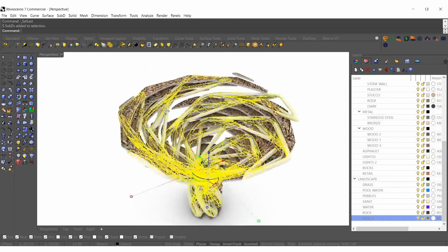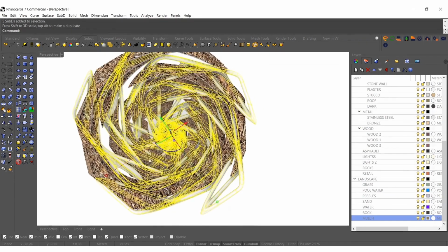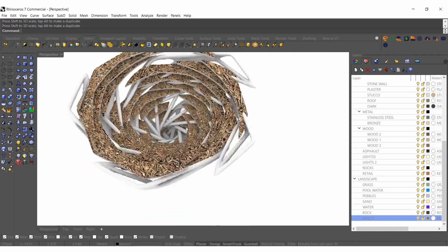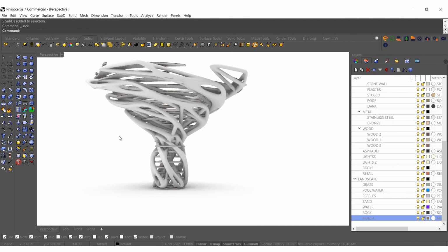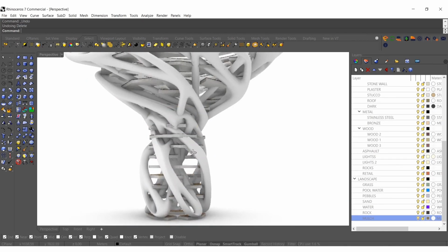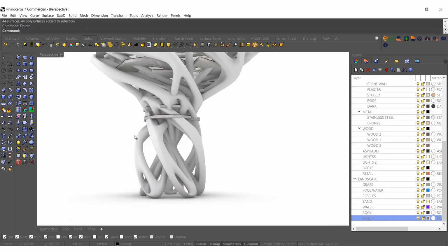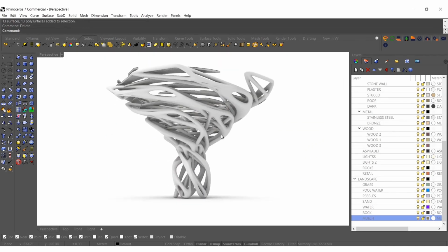The new stuff, I might just scale it in Rhino real quick, just in the X and the Y, so it gets outside those floor plates a little bit more. And then these floor plates down at the bottom, just going to delete them out. Ooh, that didn't work out like I thought. Let's just delete out these maybe. And the ones that are really intersecting. So something like that.